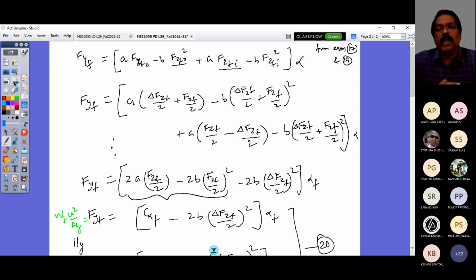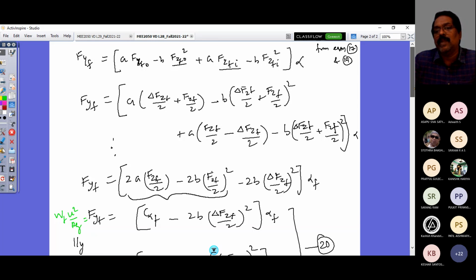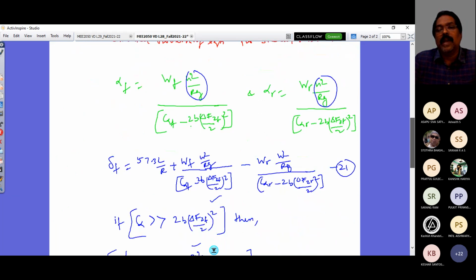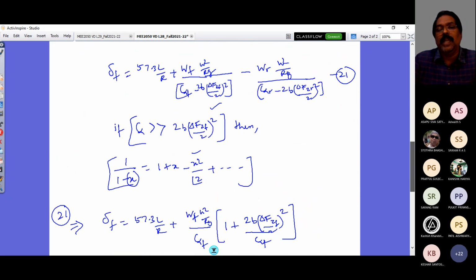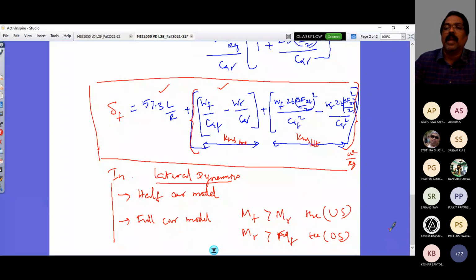And we have also accounted that our tire is not a linear tire model. It is considered to be a non-linear tire model. Hence, the cornering stiffness is expressed in terms of normal load. That is exactly what you saw in the last class through this derivation. And we ended our study looking at the effect of the consideration of suspension and non-linearity of tire on our understeer gradient. That is what we could witness clearly here.